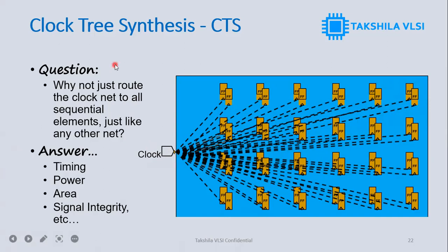So it is necessary that we place some repeaters in the clock path, such that the clock which we give at this point reaches the sink pin of the sequential element. So this is nothing but synthesizing the clock tree. So completely giving the clock tree structure and balancing the complete tree is nothing but the clock tree synthesis.